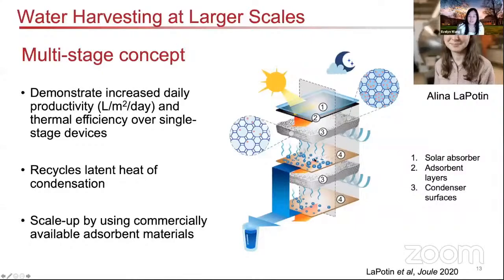And we can now take advantage of the condensation heat and recycle that latent heat of condensation to drive desorption from a subsequent layer. And through this process, we can demonstrate increased daily productivity, which is captured by how many liters of water over the area per day, and also higher efficiencies compared to that of a single stage. Also, because we're using this kind of infrastructure, we needed to now explore other materials that are more scalable. And so we've been looking at zeolites that are commercially available such that we can actually extract a reasonable quantity of water.